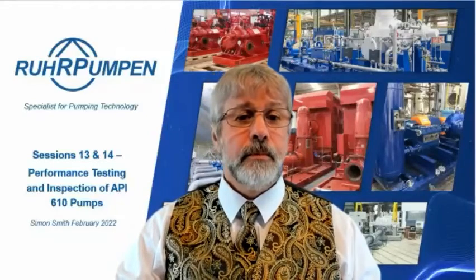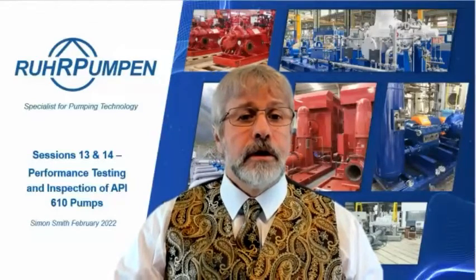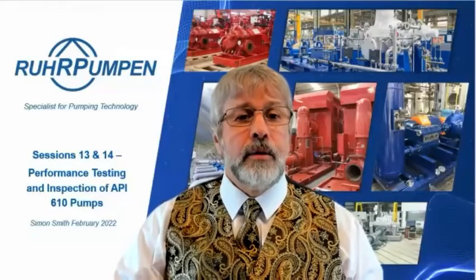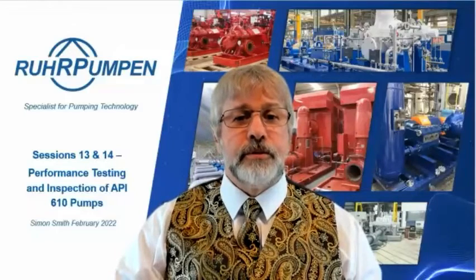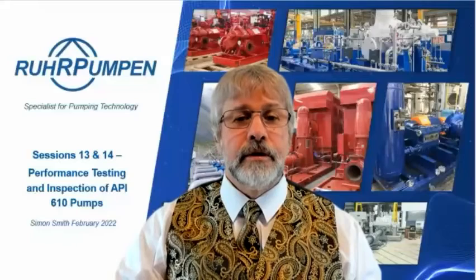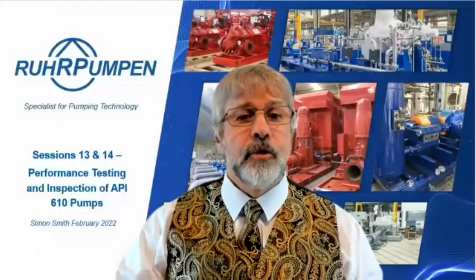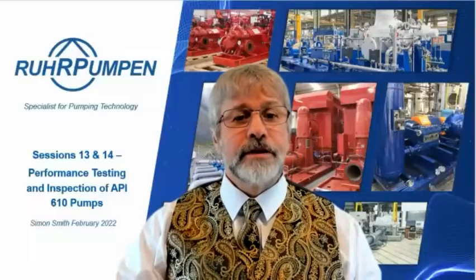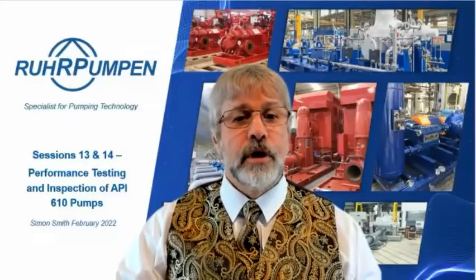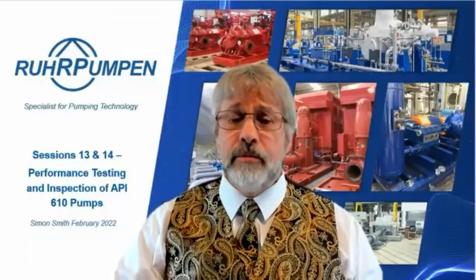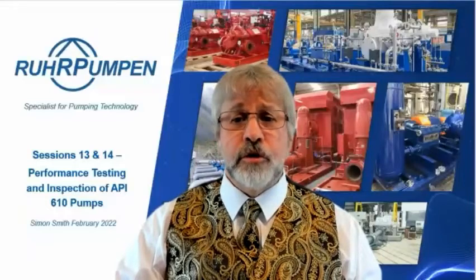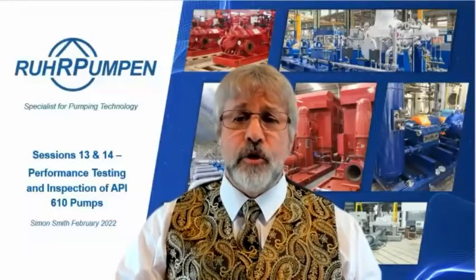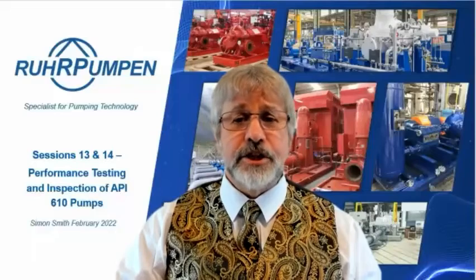Carlos Mallow again, when it comes to dismantling after successful performance and running test, for which type of pumps do you recommend strip test? None of them? Only multi-stage pumps? Which scope? Only bearings? That's a good question. API 610 requires it for pumps of more than 3 stages, so it's usual on those.